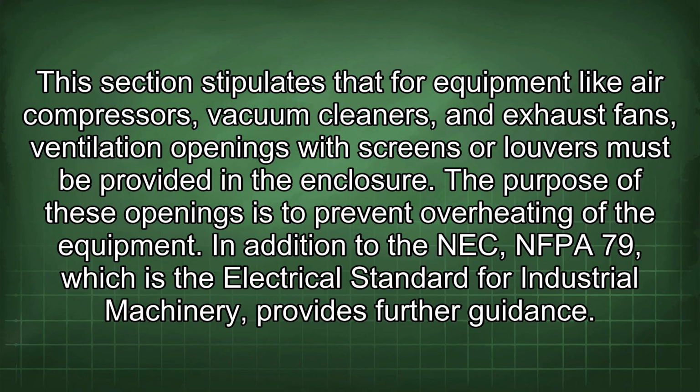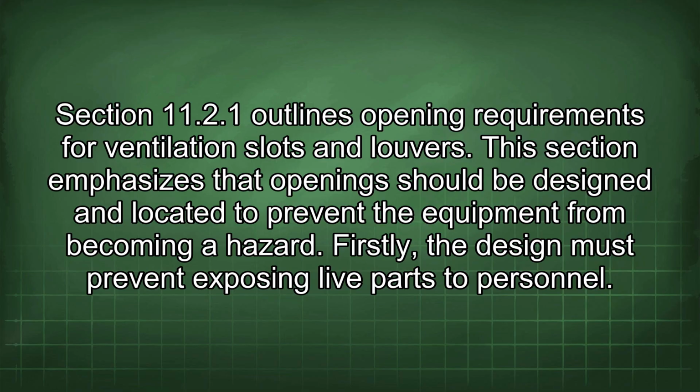In addition to the NEC, NFPA 79, which is the electrical standard for industrial machinery, provides further guidance. Section 11.21 outlines opening requirements for ventilation slots and louvers. This section emphasizes that openings should be designed and located to prevent the equipment from becoming a hazard.